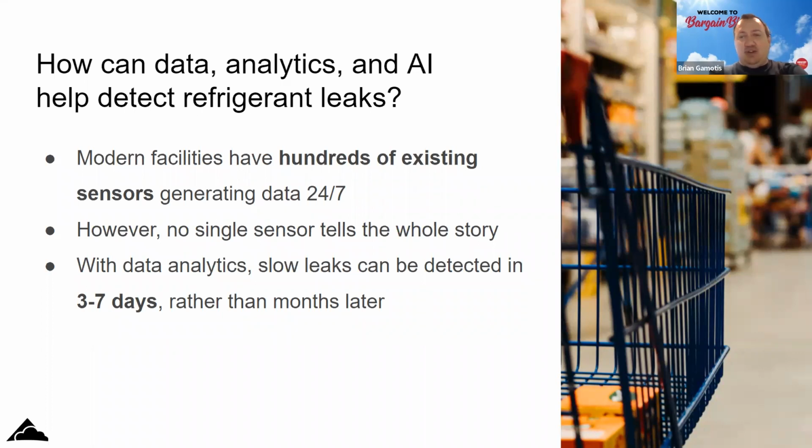I had customers with some pretty good size racks, so every spring I'd have service calls for a handful of stores where we'd find leaks and then dump 300-400 pounds of gas in. That's a lot of juice and a lot of coin. So to not take advantage of using other sensors and combining the data to get better refrigerant tracking on your levels, it'd be crazy not to.